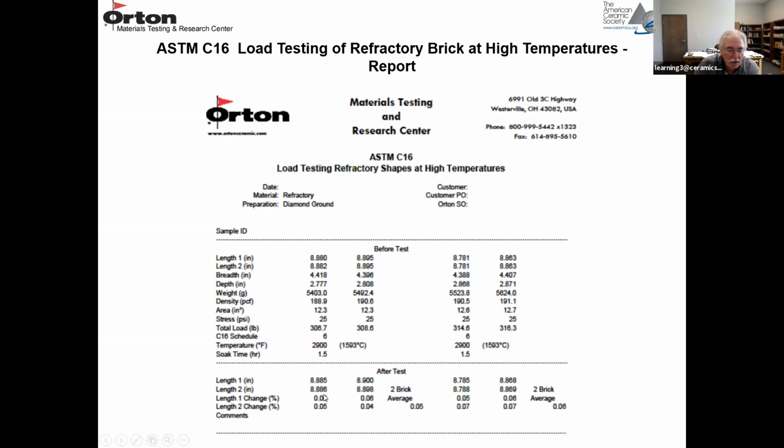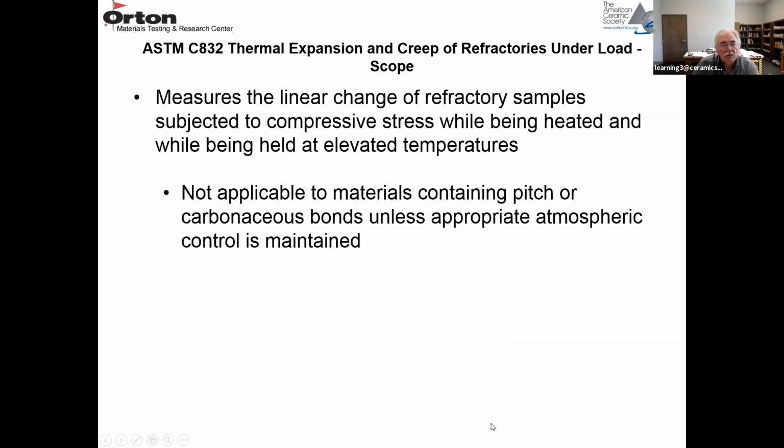So the growth of a second phase in this material was a little bit larger than the amount of creep that took place. So this is the before and after test. The before results and after, you don't know really what's going on at all in between. But that's why I said it's a pass-fail test. But it's a test that's easy to run, and you can decide whether refractory fails or creeps rather easily. So before and after test, that's a test that's commonly used. The more sophisticated creep test is where you monitor the change in length throughout the entire test.